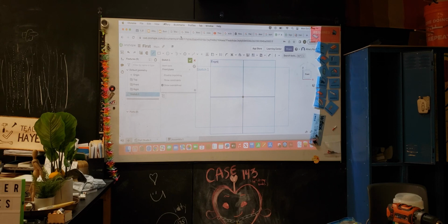Okay. Alright, so the next cool tool we can do with Onshape is construction lines. So it's like a line. You can click line up here, and then you can click over here where it says construction, and that will activate construction lines. As opposed to a regular line, construction lines don't need to be specified by any length. They only serve to benefit your drawing, or they act as guidelines for your sketch in different relations. Construction lines are a good way to define other things that are otherwise undefined.